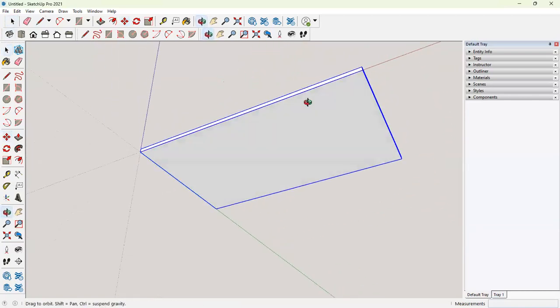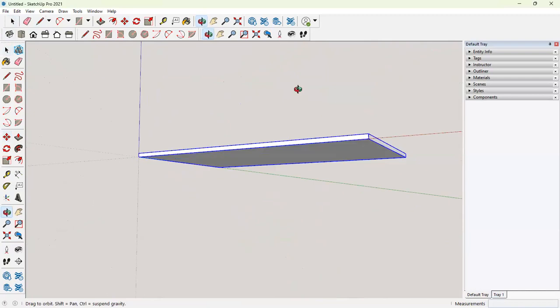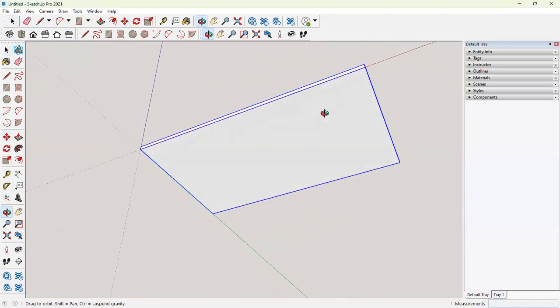Now we want the legs, so we will go to the bottom side. Dilal, last time I didn't explain that we have guides, like we use drafting lines in AutoCAD. In SketchUp also you can use that. To activate it, you can either go to your tape measure tool or press T on your keyboard.